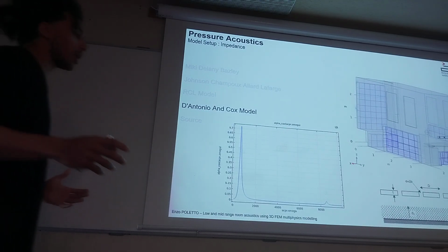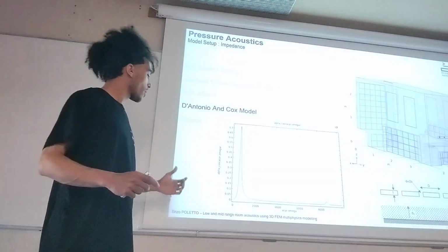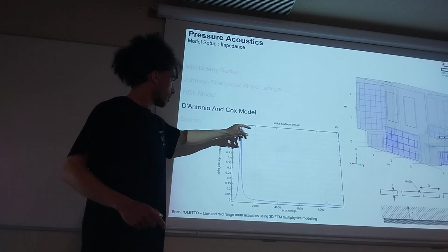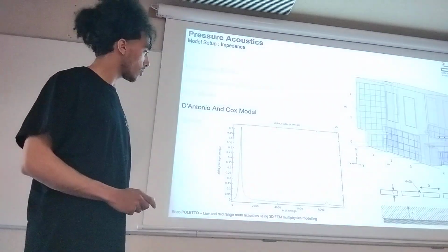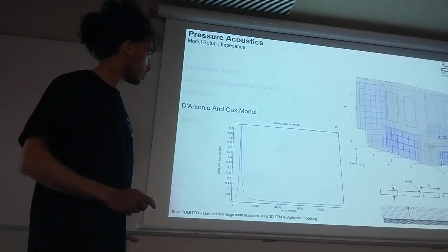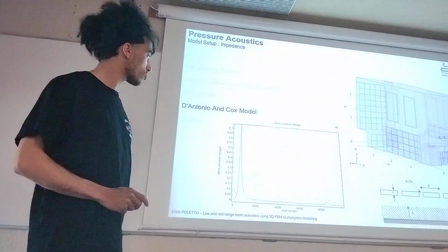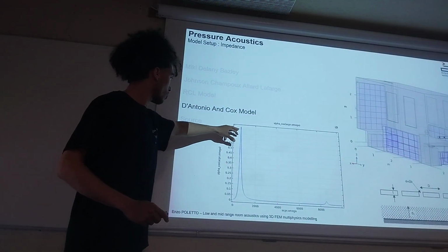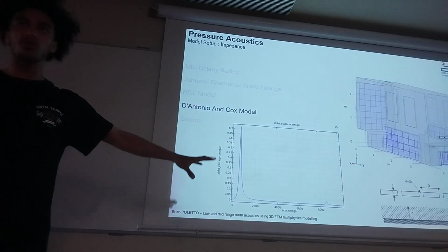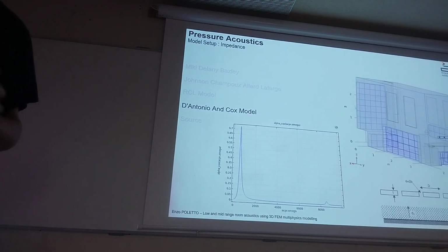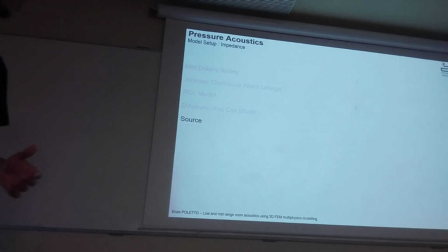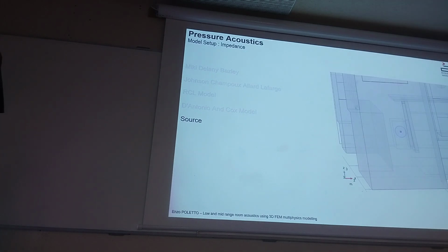So when I launch my study, whenever I'm at the resonant frequency, I'm going to have absorption happening on every one of those walls selected, at a magnitude this time around of 0.7. That was an earlier version. We saw we were about 0.35 for the resonators, but hopefully you understand the principle.